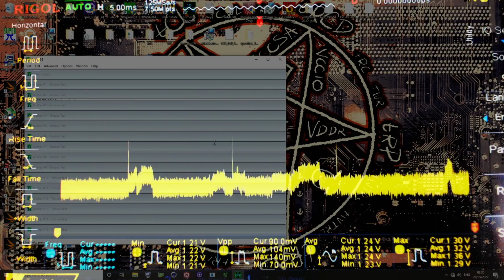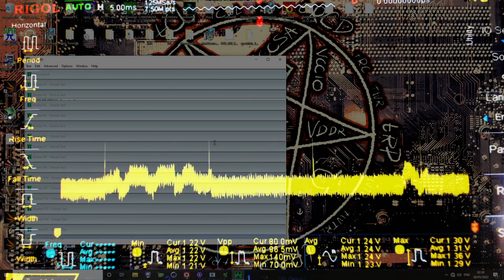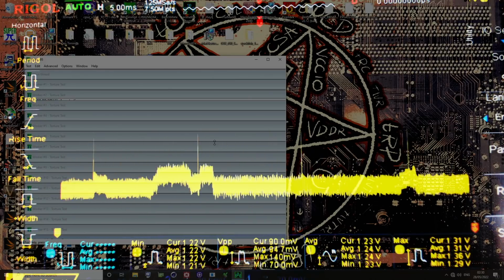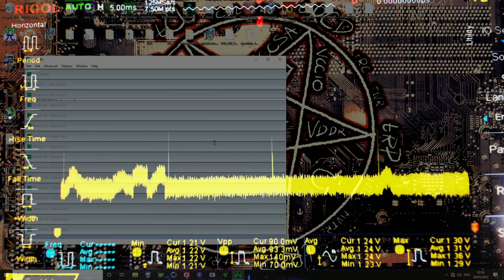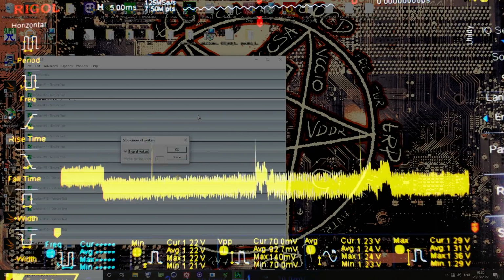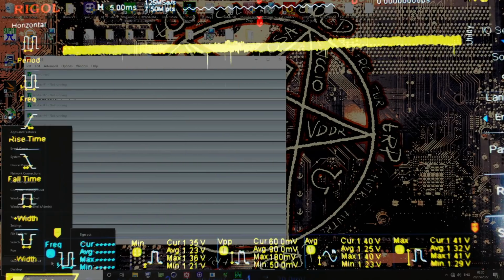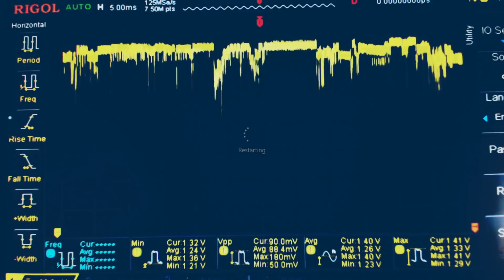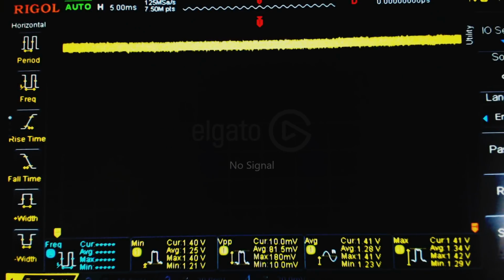As the CPU heats up, I imagine the voltage will actually climb up a bit, because the CPU starts pulling a bit more current, and also the socket impedance probably gets a little bit higher as the temperature of everything goes up. But this is 1.24 volts, so that is matching the data I've recorded so far. There's no mistake in what I recorded. So what happens when I switch it over to 1000 kilohertz?